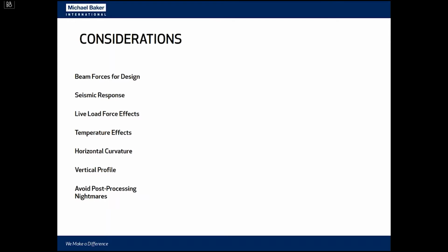We also had a custom design live load criteria, since many of the trucks that we designed for on highway bridges can't even make it up the driveway because of the geometry. So we came up with our own more appropriate live load criteria. The owner also had some concerns about potential maintenance of expansion joints. So it was decided the bridge would be modeled and designed as a rigid frame, and temperature effects would need to be considered.